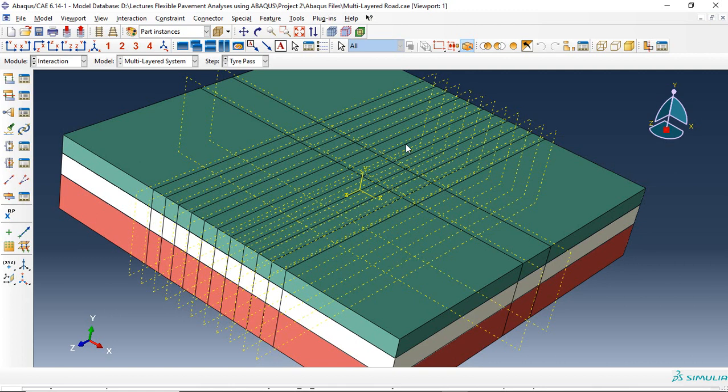And make sure you see why it's easy to get wrong. This is very important. Ignoring the tire patch geometry or pressure distribution can lead to underestimating the fatigue life sometimes, if you are working with fatigue. And overlooking shear failure in the asphalt layer also gives incorrect rutting prediction. So it's very important to consider these accurately. And you need to make sure that the FEM reflects the real-world pavement. That's what the effort you are doing is for.